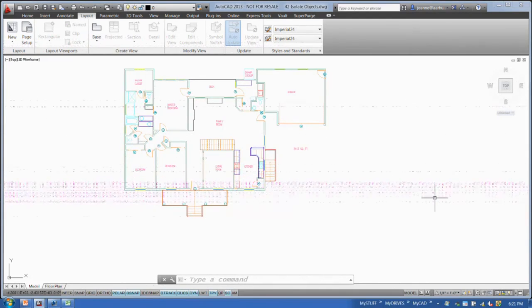Oh, I'm not a Civil 3D person, so I don't know the answer to that. No. An XREF won't work with this because it's just one thing. But you can clip an XREF and then that works. It doesn't have to be a permanent clip. You can temporarily clip it.